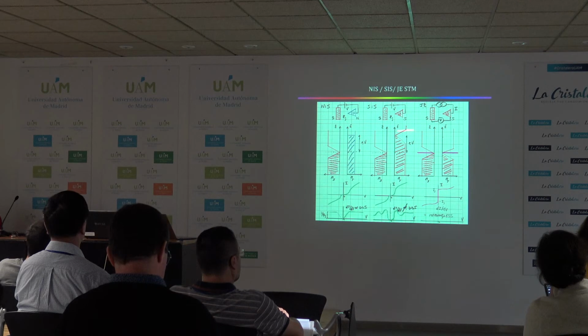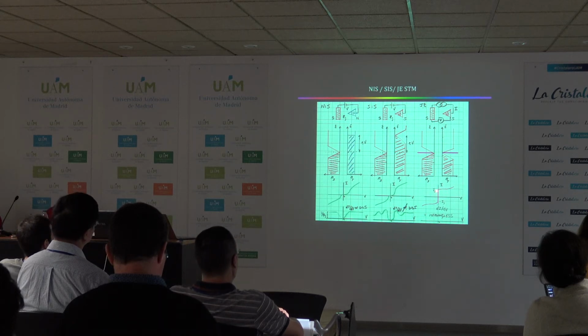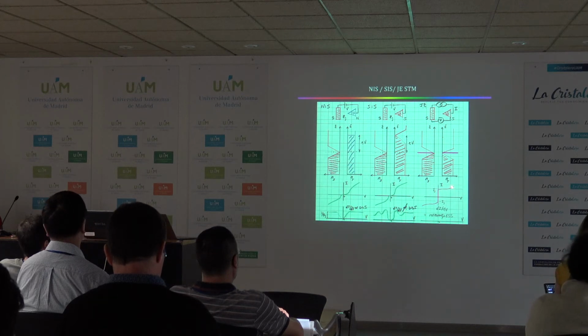That's Josephson tunneling. So provided the current being delivered is less than the Josephson critical current, the condensate Cooper pairs will tunnel. And when you reach the Josephson critical current, which is a geometrical and thermodynamic property of the junction, then the system will spontaneously develop a voltage that you will detect. So the definition of the Josephson critical current is when the voltage appears.